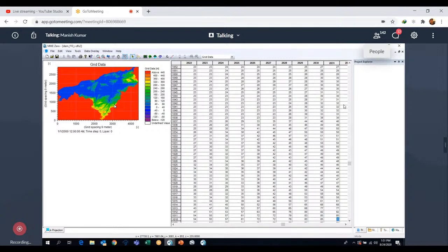It will help in the sense that suppose some highway is there at a little higher elevation, then when flow is moving, it will cause flow only on one side of that highway, because the highway is at higher elevation and it will act as a weir, meaning all the flow will be in one direction only until the flow is higher and it crosses to the other side. So the better the information available in your bathymetry, the higher quality flood inundation mapping you can generate. So this is about the base map.